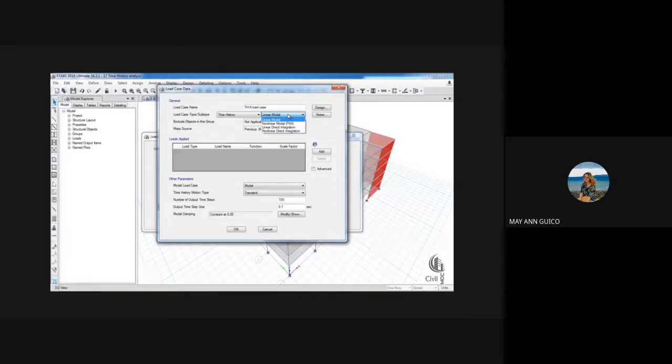It is a closed-form solution. It takes the input values of the earthquake record and analyzes them. Direct integration uses the full method, so analysis using direct integration takes much time, but it gives accurate results, to the point. Modal analysis is approximate and gives approximate results, but in much less time, within 10 or 15 seconds. So for this example, I will use the linear modal analysis.